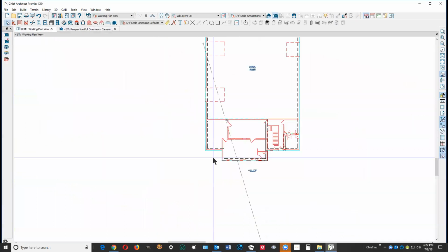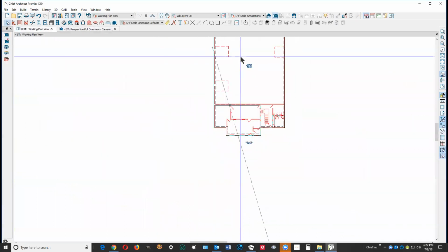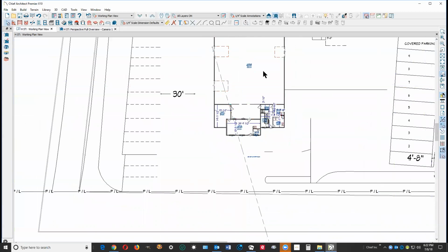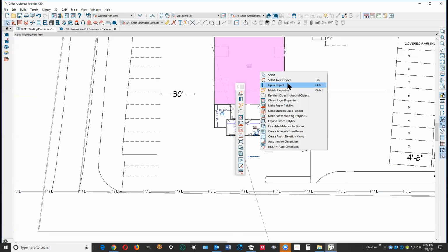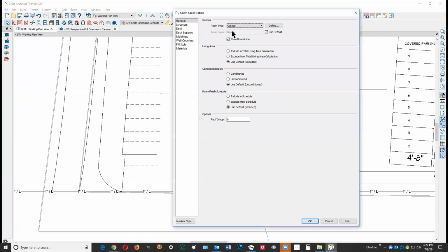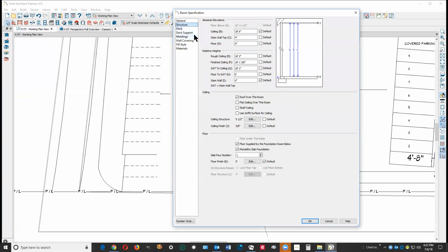Like back here in this area where you've got the garage doors, let me go up a floor. Turn the reference off. This should be at -6. And of course, an area like this is going to have a slanted floor, slanted towards the doors for drainage purposes. Let's see what the floor level is. I don't see a floor. Oh, there it is. Oh, it's 4. It should be -6.